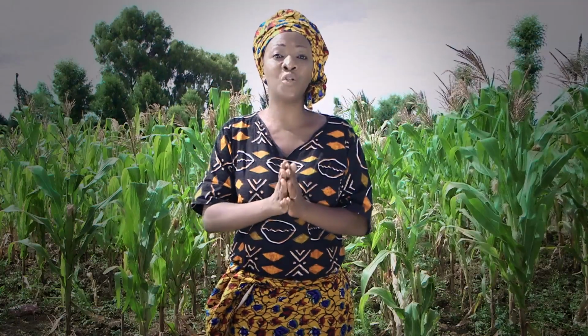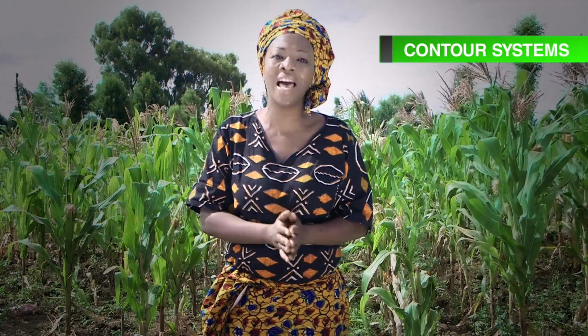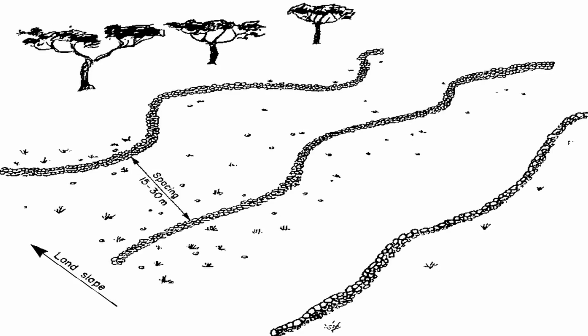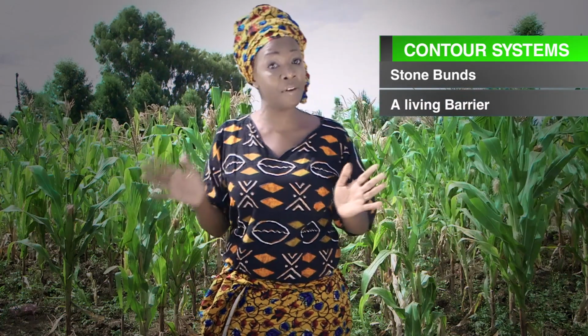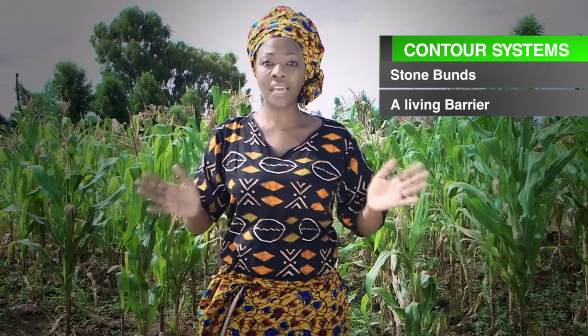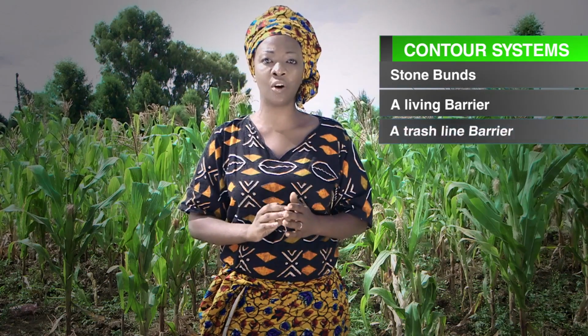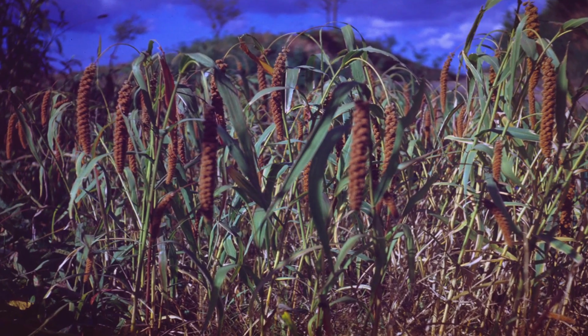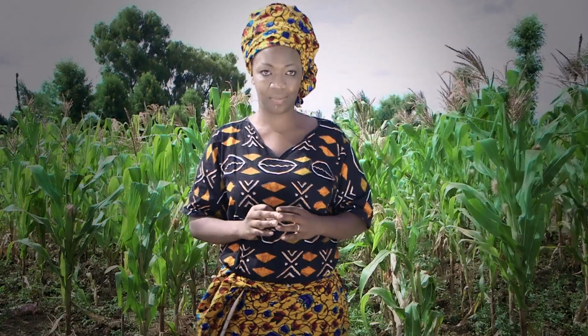The simplest form of a contour water harvesting system is stone bunds along the contour line. They slow down the speed of runoff water. A living barrier such as grass or other vegetative material is planted immediately above the stone lines. A trash line barrier is one that utilizes crop residues like millet and sorghum stalks. This is also used to reinforce the stone lines. At this point in time, we will do a series of exercises as concerns water management, the making of stone bunds, and the making of zai pits.